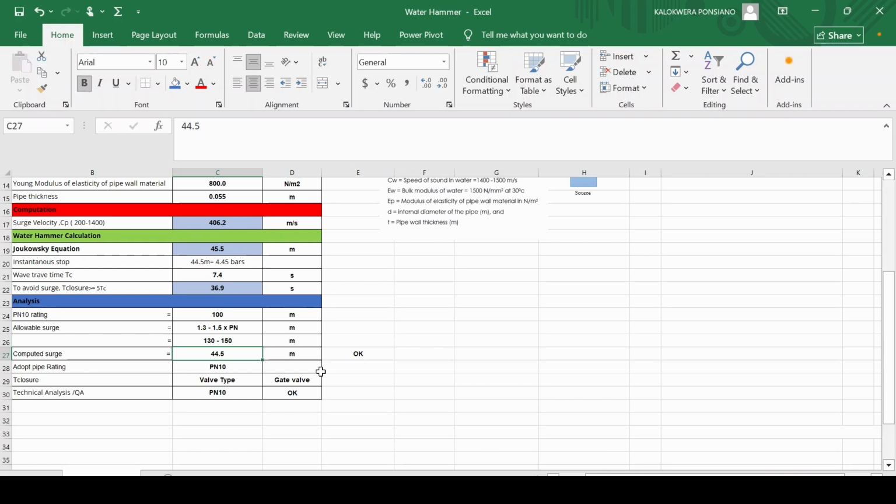So from here we can learn that material selection is not only structural, it affects hydraulic transients. As an engineer, after this calculation, you're supposed to know how to choose the type of pipe you're going to use. But for complex transmission systems, simplified equations are normally insufficient. So we will be required to perform full transient modeling for our system.